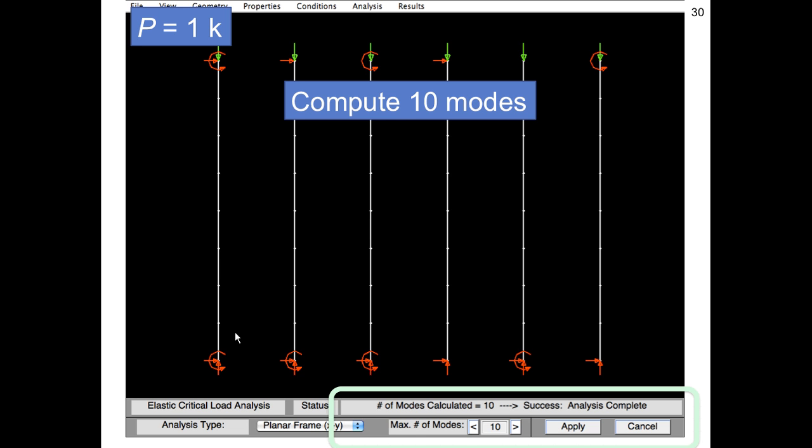And I've got different boundary conditions. These red arrows imply restraint. You can see this particular one in the lower left is restrained from moving up and down. Well, of course, we need to resist the axial force. But it's also restrained from moving left to right, and it's also restrained from rotating. If we move all the way across, we can see the first few are what we would call fixed support conditions. Then I have a pinned support condition, then a fixed support condition, and then a pinned.